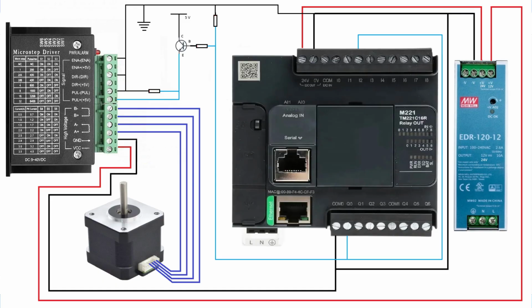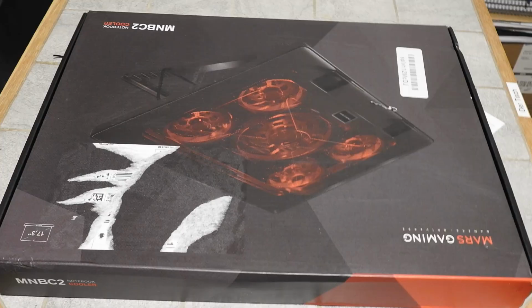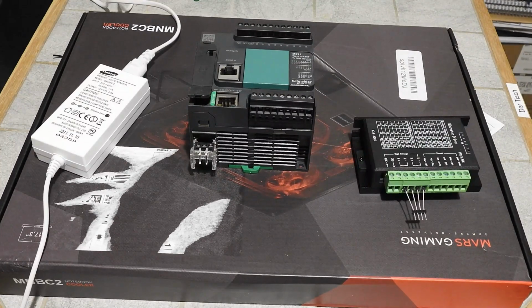As we made the enable pin connected to 0 volts, the direction pin connected to 0 volts, and the pulse negative pin connected to 0 volts. For the PLC pulse feedback for the fast counter, wire the fast output Q0.0 to the input I0.0. Let's now speed up the video for the wiring of all the components in the project.